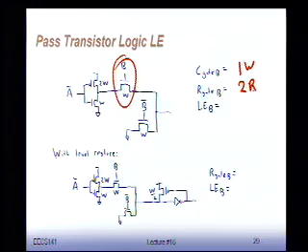So I look at the logical effort. My resistance has gone up by a factor of 2, but my capacitance has gone down by a factor of 3, so I get a logical effort which is equal to 2/3. So I win. From the B input perspective, I'm better than the inverter. From the A input, I'm actually worse. Which shows that this is a fairly asymmetrical gate.